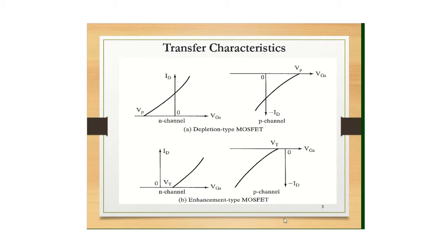So in terms of MOSFET, it would have been drain current versus input gate current, that is IG, which would have been in the order of 10 to the power of 9, all right? But since the gate draws very small leakage current, this current gain is not an important parameter.